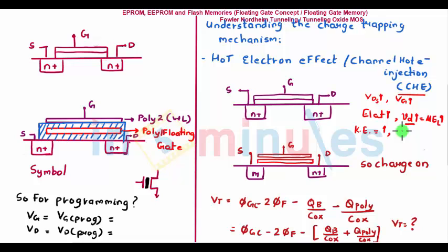They were hot electrons, and these electrons moving with very high energy underwent a process called impact ionization, which means that the high energy electrons pass enough energy to other electrons so that they can move from the valence band to the conduction band, therefore creating a hole in the valence band, or an absence of electron in the valence band. So an electron hole pair was generated. Holes, being p-type, will move towards the p substrate in case of an NMOS and will lead to substrate current. However, the electrons might move towards the oxide if the gate voltage was very high.